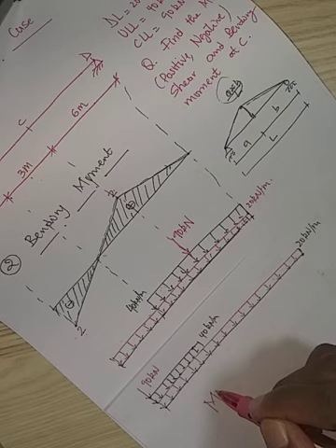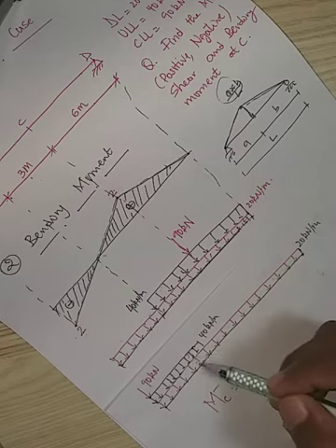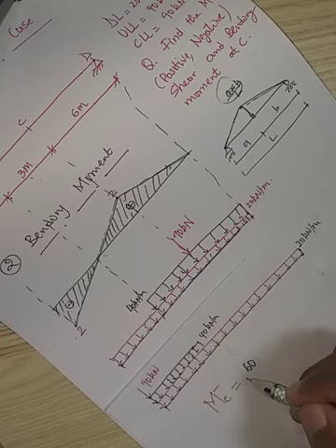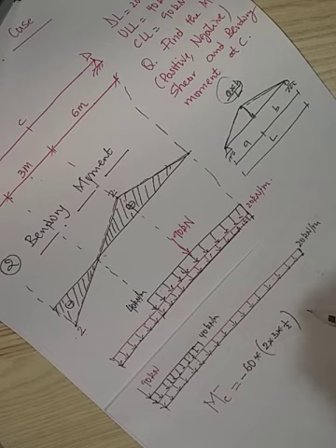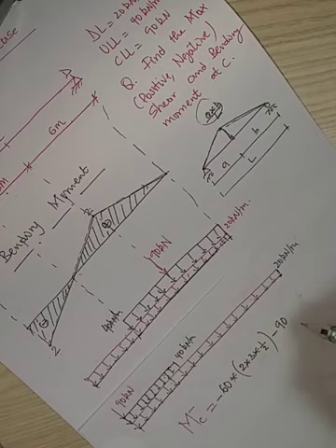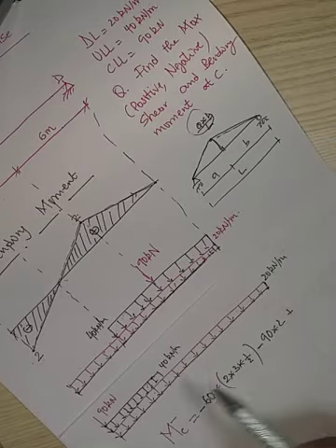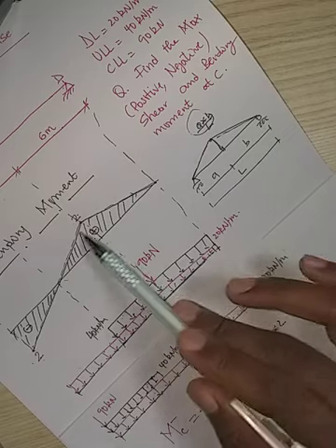So let's calculate the maximum negative bending moment at the cross section C. It is equal to the sum of these values. Here we get 60, but negative because it's applied on the negative section, times 2 is the height here, times 3 is the length, times the half. Minus 90, the concentrated load, times 2. And then plus this dead load, but applied only on the positive portion.